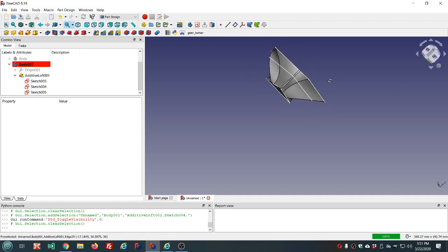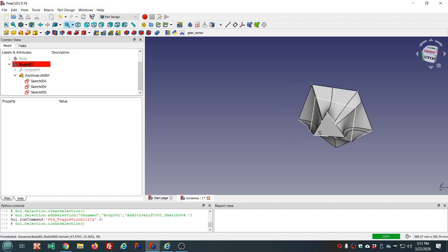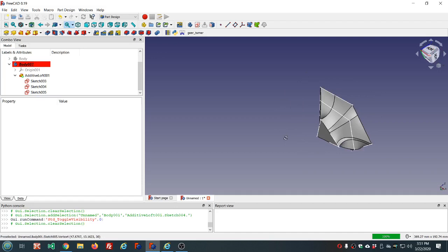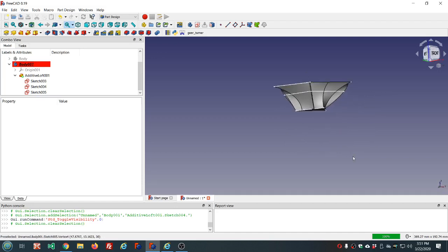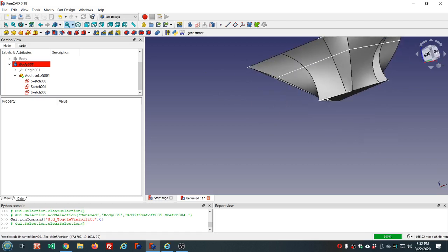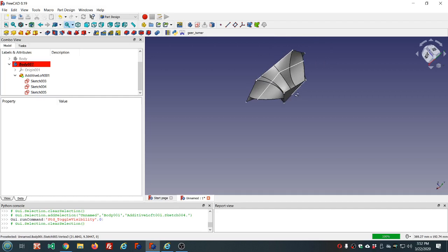You obviously need an edge going to each of these vertices, but you cannot connect each vertex to a vertex in the triangle sketch, because you only have 3 down there and 5 up here. This means the software has to decide how to make these connections, and this means you, the designer, have less control.